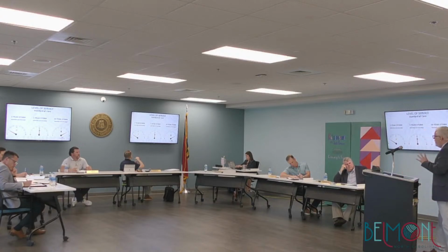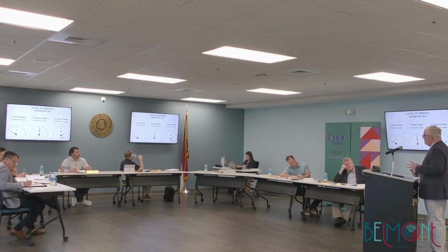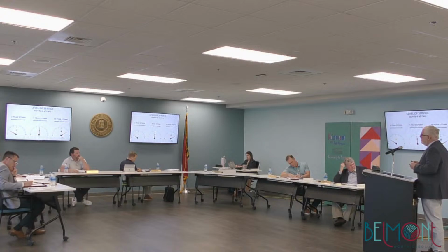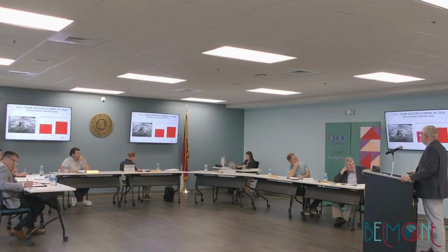And so I want you to think about level of service or standard of care in those terms. What is the right balance of investment to reach that standard of care, versus under larger weather events that you may actually experience SSOs, or sanitary sewer overflows? And that's obviously what we're trying to prevent, or prevent things from backing up in homes, whatever it may be.